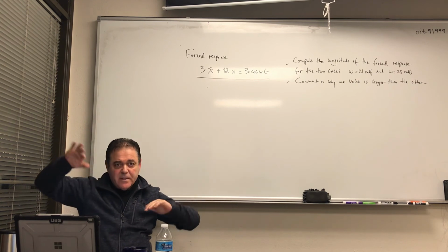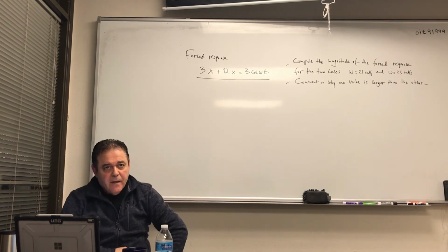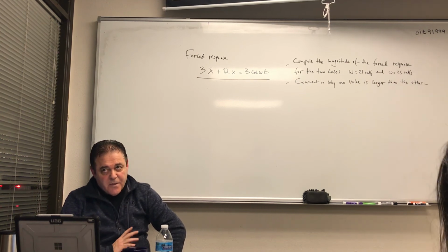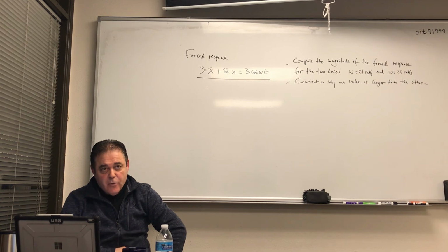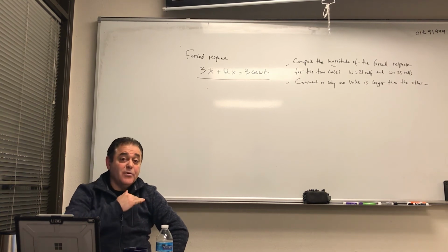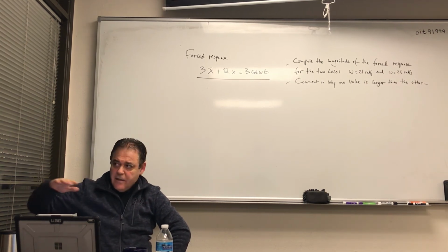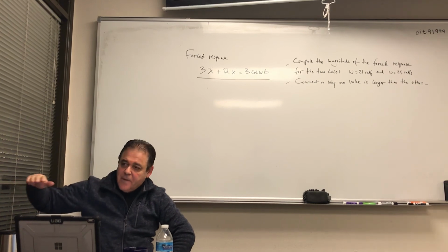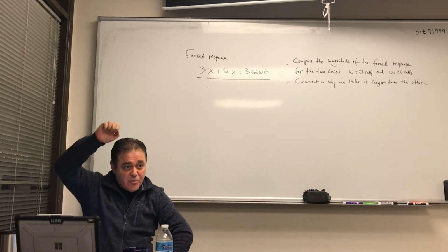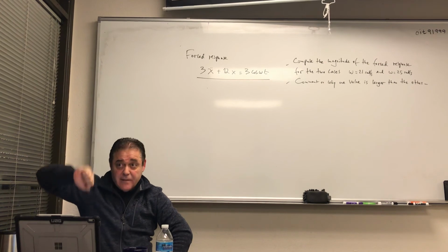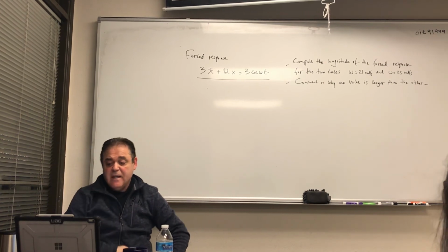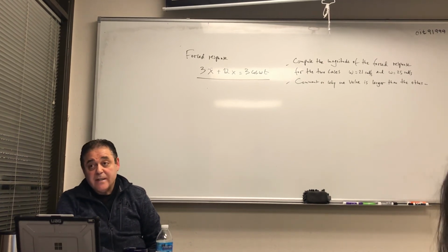So it's the steady state? Yeah, the steady state is the forced. The books call them all different things. The homogeneous one the book calls the transient one, the one that dies out. And then what remains is really what you are pushing on the thing. In other words, the mass is eventually going to vibrate at exactly that same frequency.